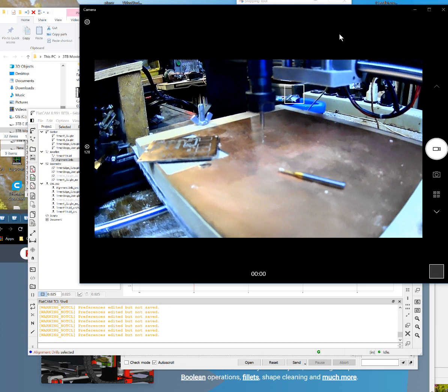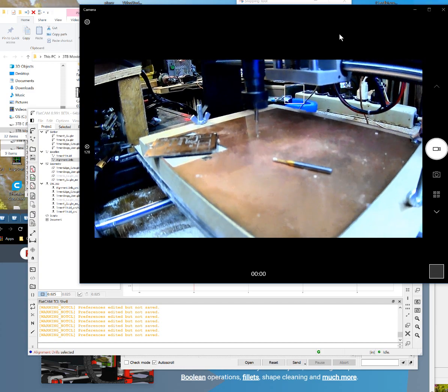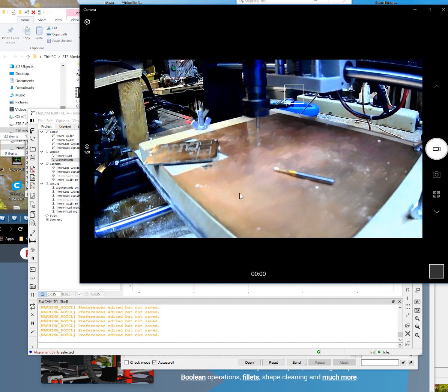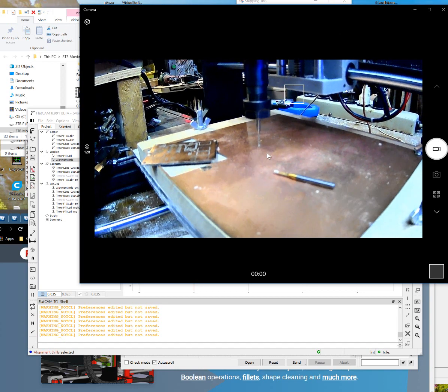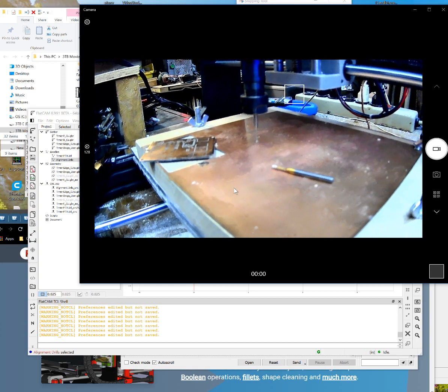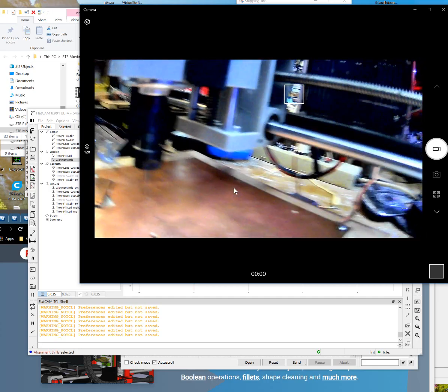That's why I couldn't find it. I had it actually in the spindle there. But that's the first tool I actually use, is drilling those 2 reference holes. But the first thing we need to do is actually make a height map, and it doesn't really matter what tool you make a height map with.